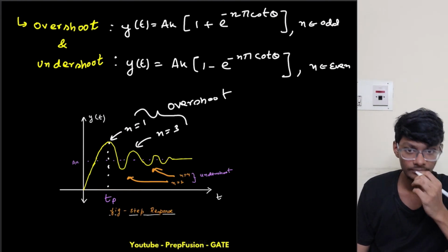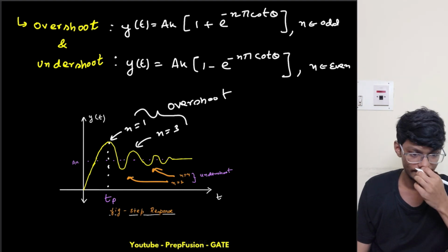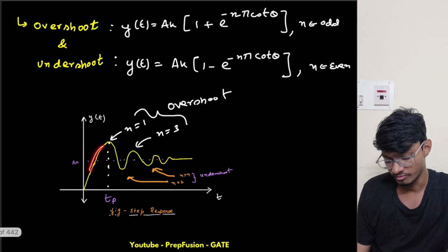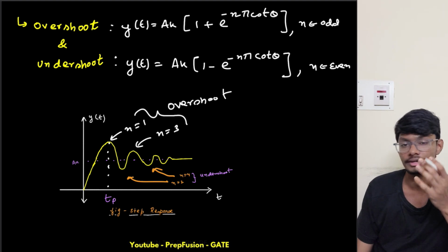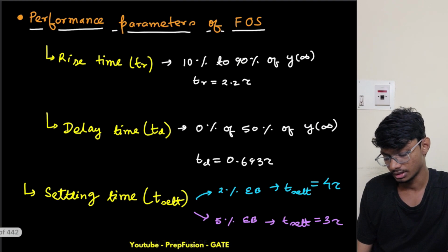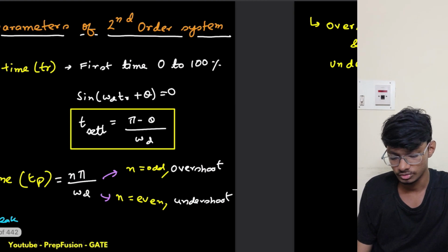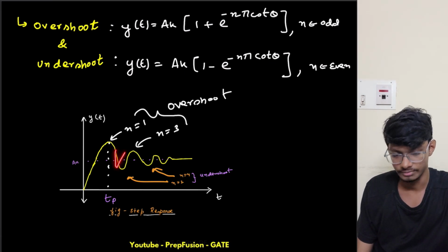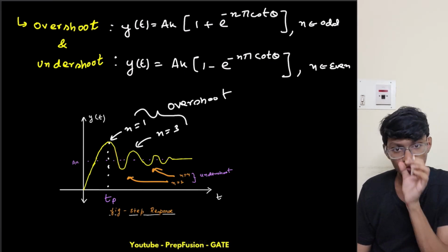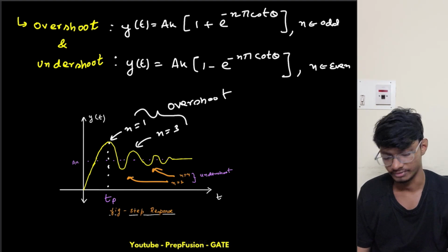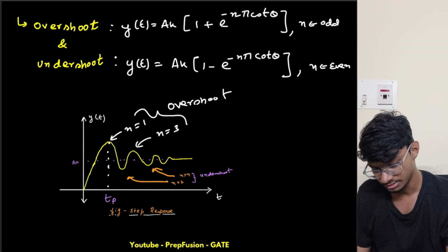And what about the settling time? Obviously I can't say, it will go above this 95% many times. What was the definition of settling time here? 90%, right? So it will go above this 90% multiple times. So how will I define my settling time? It will be within the error band, positive and negative. So my error band will be something like this.